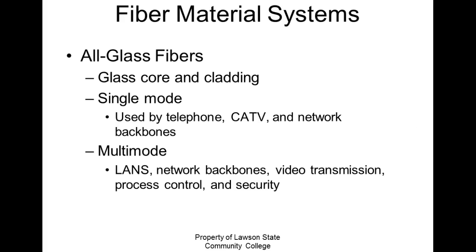All glass fiber runs a glass core and a glass cladding. That's what we use. So this is used by a lot of single mode fibers, which is used by the telephone company, CATV, and network backbones. A network backbone is the connections or the conductors that carry everybody.